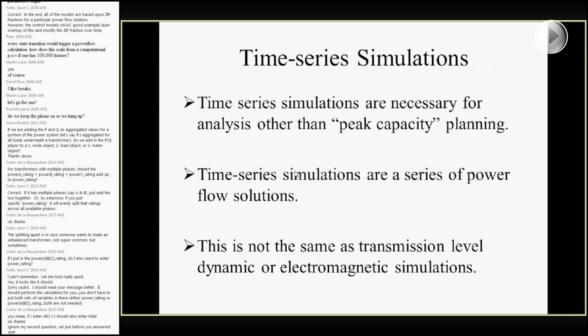This is not a dynamic or an electromagnetic simulation like you might experience on a transmission level, particularly if you're using something like PSLF or, what's the other one? PSSE, yes, the PTI solver. I couldn't remember what the name of it was. They'll do the static power flow as well, but then they also transition into the dynamic solver, where they will give you the sub-second value of how your individual machines are behaving. This particular module, the Powerflow module, does not do that.